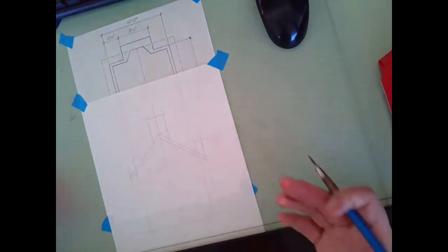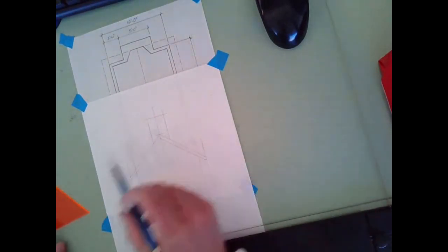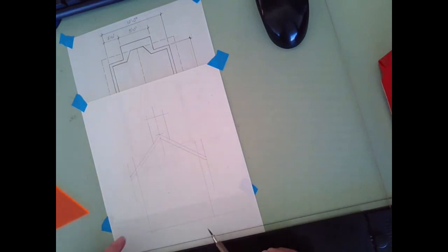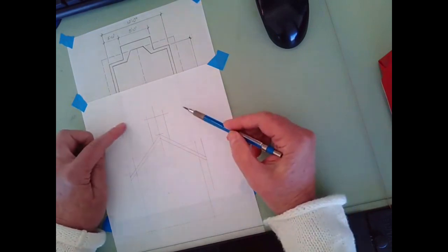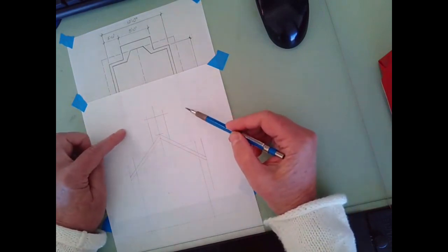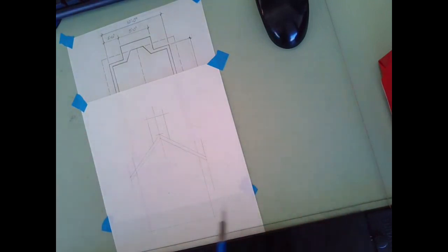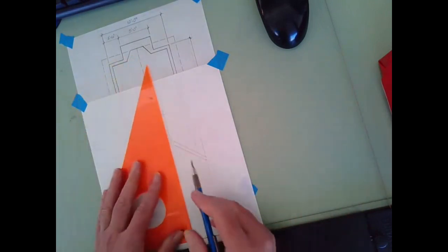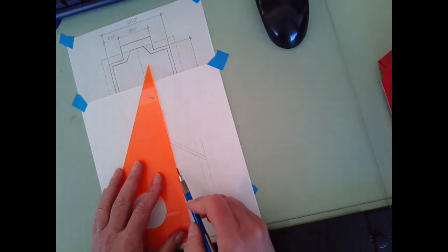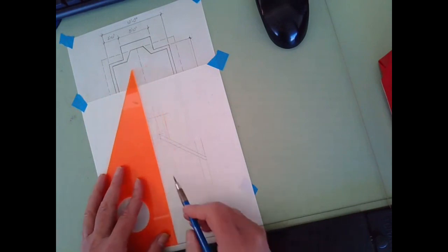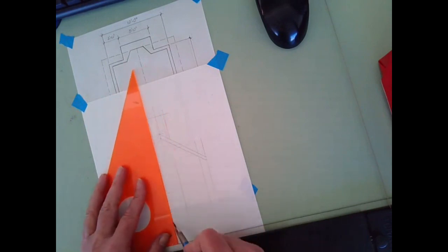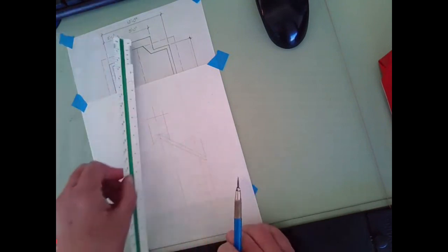So there, I've got very quickly, and if I were doing this on my own, I could have done that quicker. I was going slow for you guys, but very quickly you can see I've got the outside of my building all done because I didn't have to measure anything. I took my dimensions from the floor plan. Now the only thing I need to do now is the door. So for the door, I'm going to pull the lines down. I said the door was 7 feet high.